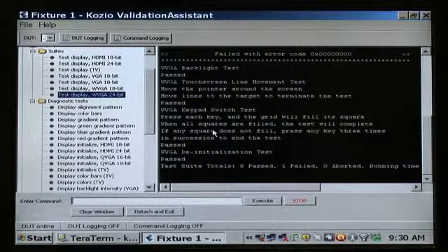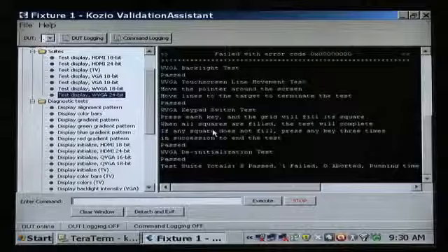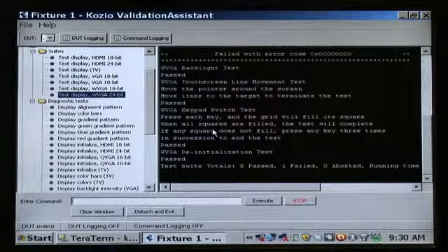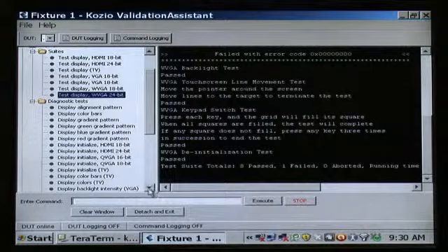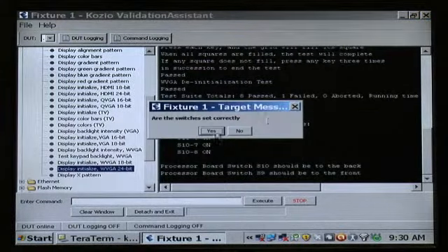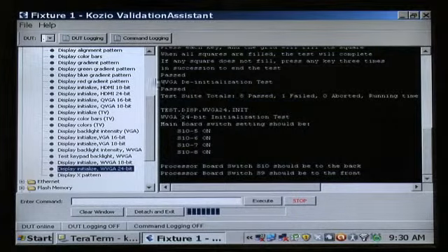We've performed a very complete user interface test in less than a minute, but we still have the error we saw in the gradient test to investigate further. The failure mode looked like it could be a stuck bit between the processor and the display. Let's isolate the problem. First, we will initialize the display and determine which of the color bytes is bad.